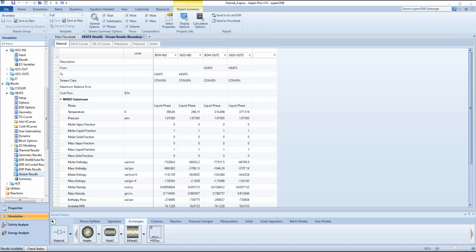And we're looking for the outlet temperature of butanol. So we're looking at butanol out 2, and the outlet temperature we have in this case is 43.34 degrees Celsius. And this is the answer to question number 10.